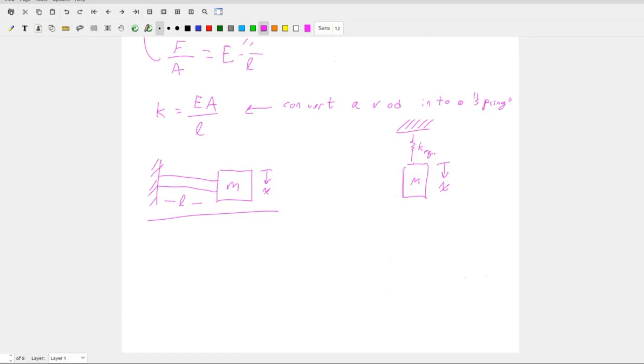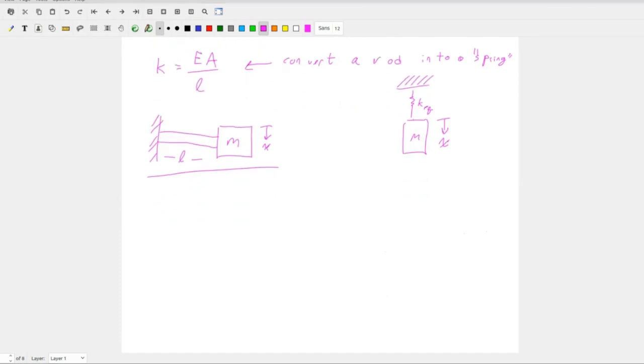Anyone remember how to calculate the deflection of a tip of a cantilever? Don't worry, there's no way I would know either. So have you seen this? Sigma is equal to PL cubed over 3EI. That look familiar? Like, oh yeah, right? That's what I think too. So this is going to give us our deflection, right? This is how we typically write it. But we're really concerned about X here. And we're just going to call that sigma because that's how we typically write it.